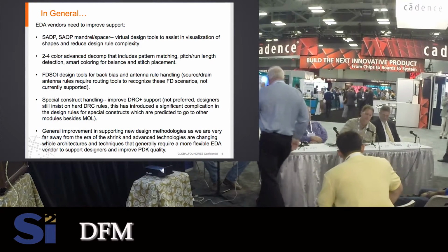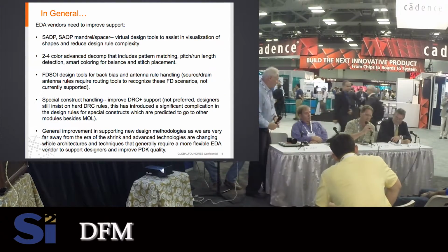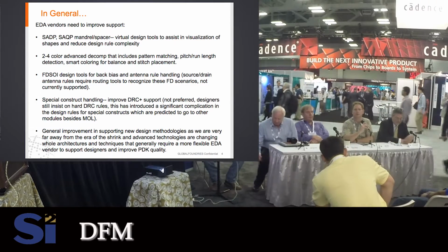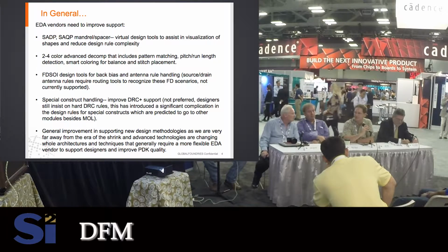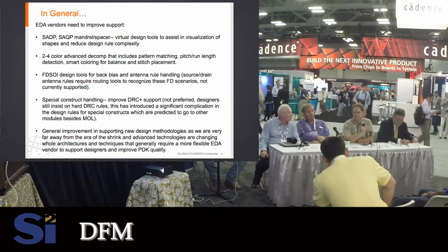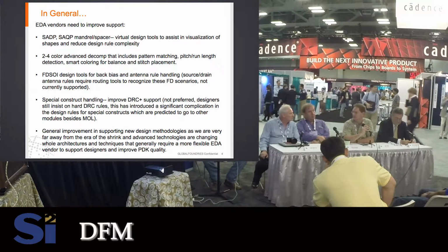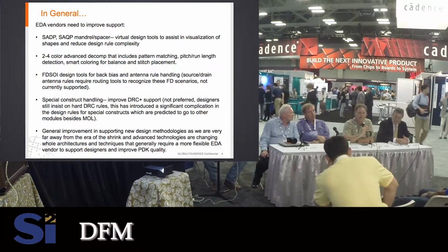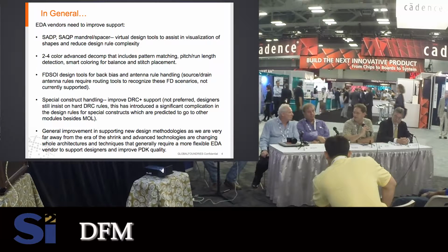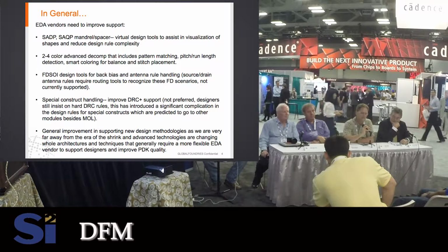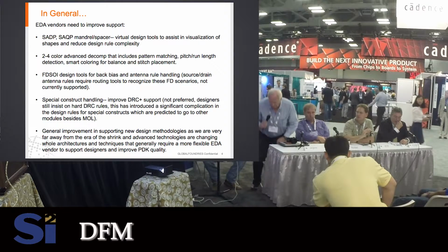Elevated voltages are basically any voltage that's above your core nominal voltage for the design process. Usually it's for analog interface circuits or I/O circuitry. Typically it's up to 3.5 or sometimes 5 volts. Or if you're in a flash specific node, it can get up to 13 volts. 13 volts. Okay.